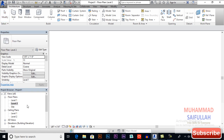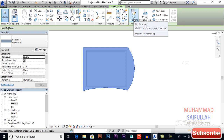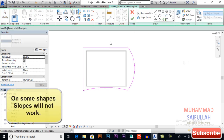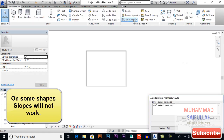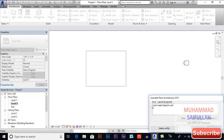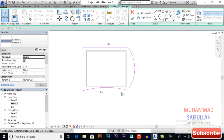Now switch to level 2. We will define slopes on it. Edit footprint. Now we will select these two and define slopes. Finish edit mode. So you can't make it in this shape. Cancel it, because I will select these two.